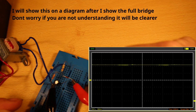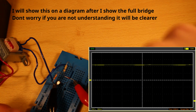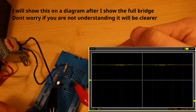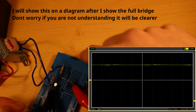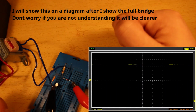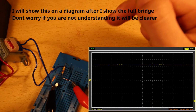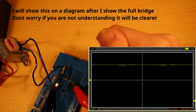Because when you're only charging on half the waveform, it means A, you're wasting half of the power because you're cutting it off. And also you're only charging it on the positive peak, so your discharge curve, if you put a load onto it, the voltage will dip much lower, rather than if you do a full bridge rectifier. So I will now cut, and I will show you what a full bridge rectifier would look like on this setup here. One second.